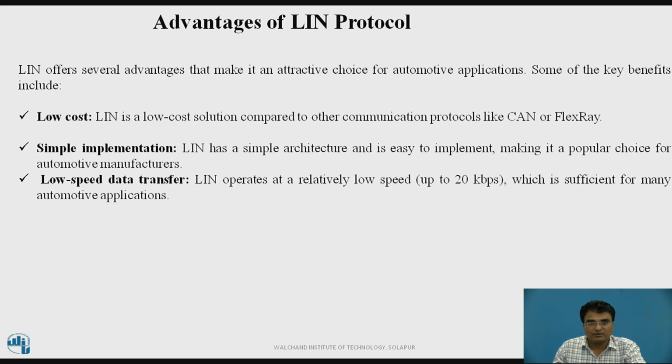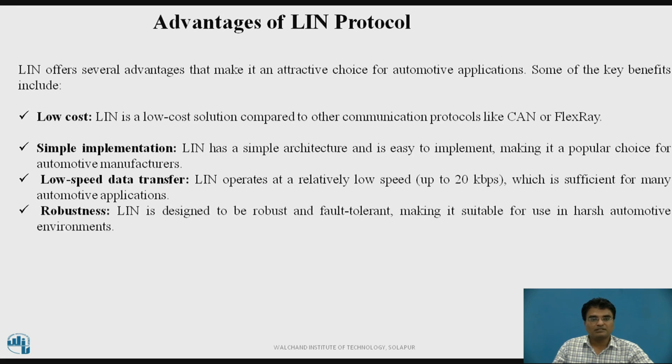Low speed data transfer: LIN operates at a relatively low speed, up to 20 kbps, which is sufficient for many automotive applications. Robustness: LIN is designed to be robust and fault tolerant, making it suitable for use in harsh automotive environments.